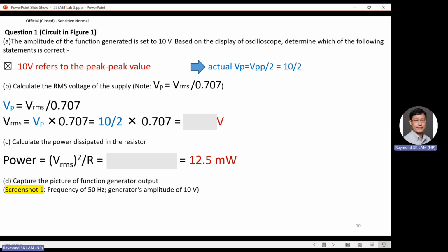So same thing, for DC circuit, you have three formulas for power, right? Can you remember what they are? I squared R, right? Okay, then you have IV, right? So over here it is the same. You have I, you must convert it to RMS for AC circuit, squared, multiplied by R. Okay. Then over here also the same: I RMS multiplied by V RMS. Okay. So this is the theory.